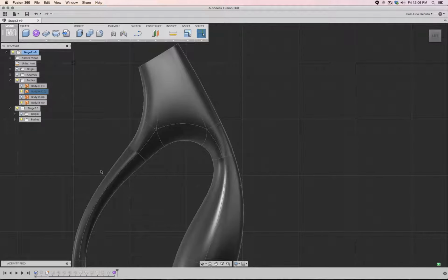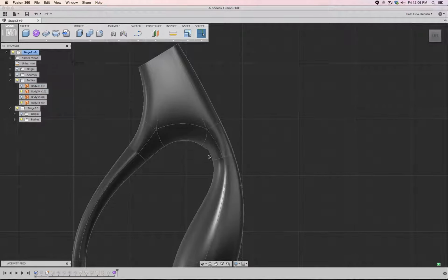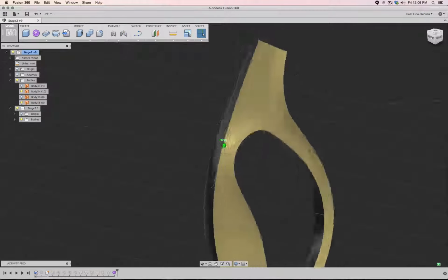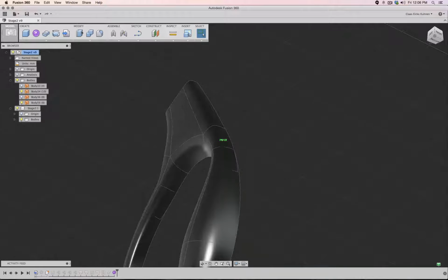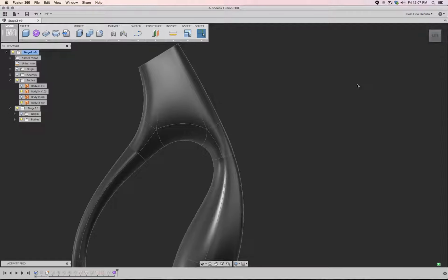And then there I could say cut, cut, cut, cut, cut, cut, and then pump all that stuff together and basically repeat what I did here. But my T-spline object I created, I had a little bit more control this way, and I changed the densities a little bit. Okay, so again, all you need to do is basically do the same steps. For example, I did here. So unsuppress.